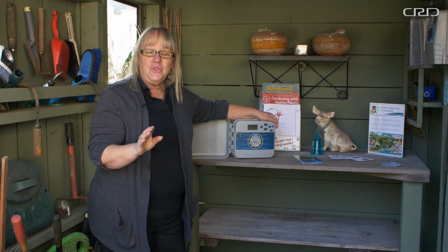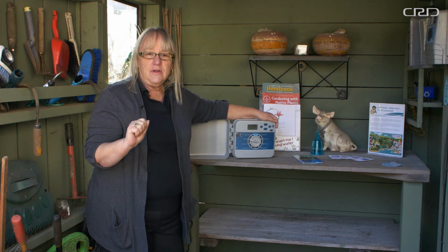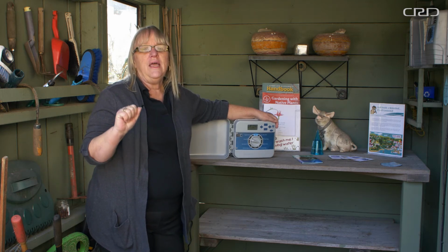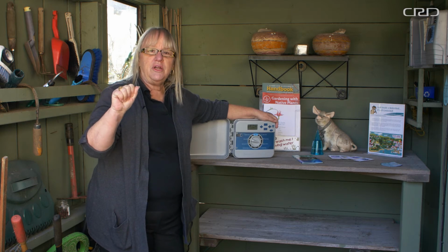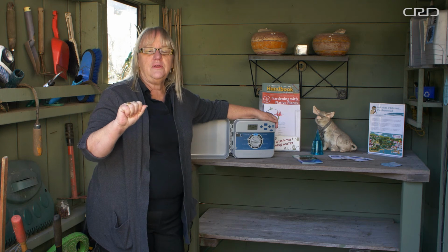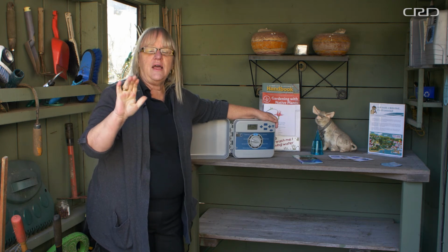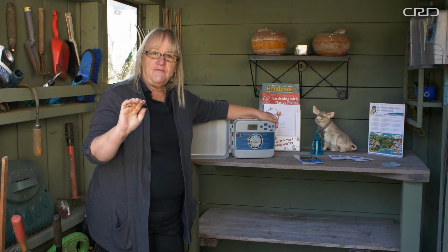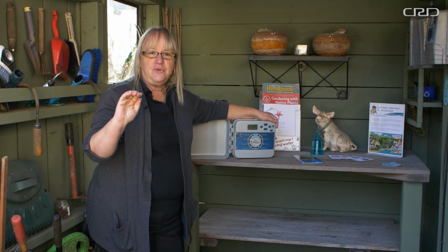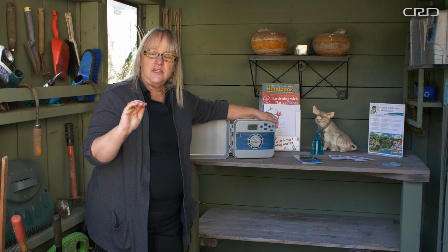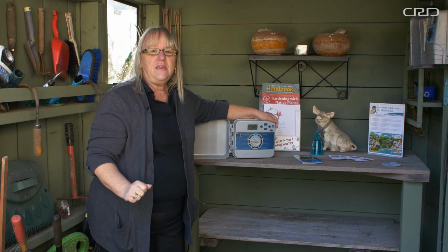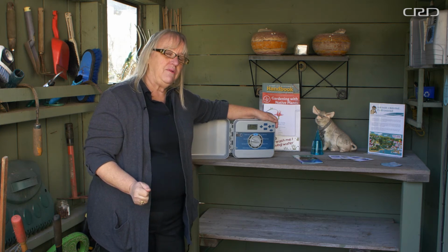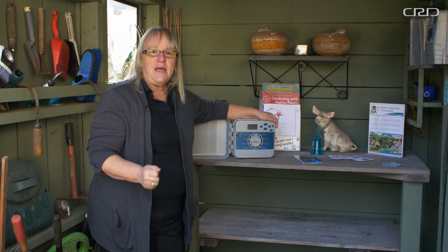So now what I've told the controller is that at 4 o'clock in the morning, I want you to come on and run station 1 for 5 minutes. When you're finished with station 1, I want you to go to station 2 and run for 3 minutes. Then I want you to wait for a bit. And at 5 o'clock, I want you to turn station 1 on for 5 minutes and station 2 on for 3 minutes. Overall, I'm getting the same maximum watering time that my plant requires, but I'm allowing it to soak